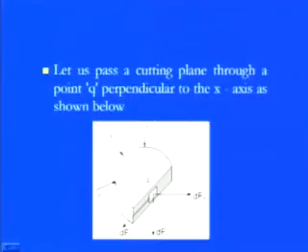In this figure, all the forces are being applied to the object, and at this particular point we have chosen a small segment whose area is delta A. Because we have chosen three different directions, in those directions the forces are acting. In the x direction, the force dFx is perpendicular to the area. But the other two forces, dFy and dFz, are not perpendicular to the x-axis; they are parallel to the area.